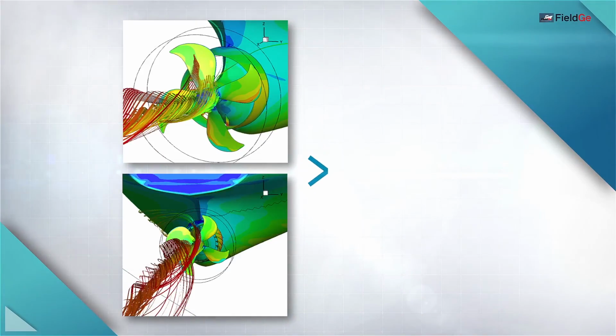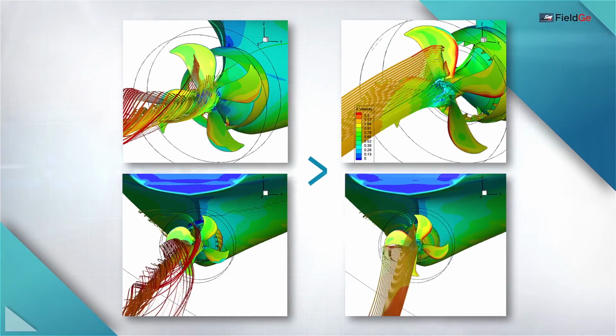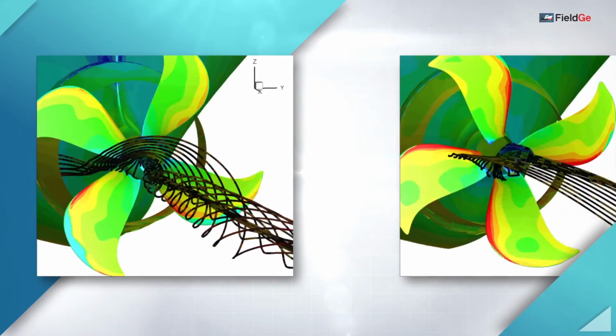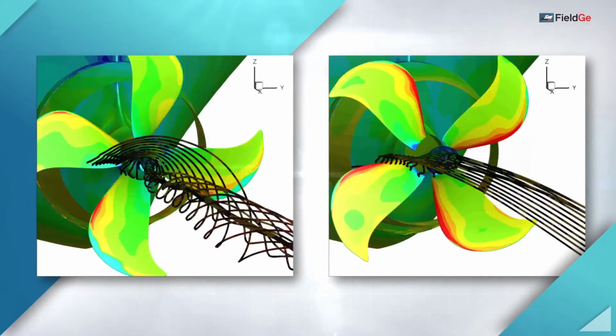The following figures show a difference in the presence or absence of the reduction device. This vortex is relatively strong and can be dangerous because it can lead to erosion of the rudder located in the propeller race. These devices can get rid of these vortices generated around the ship. Consequently, it can also contribute in reducing vibration and noise. The difference can be clearly observed in the clip.